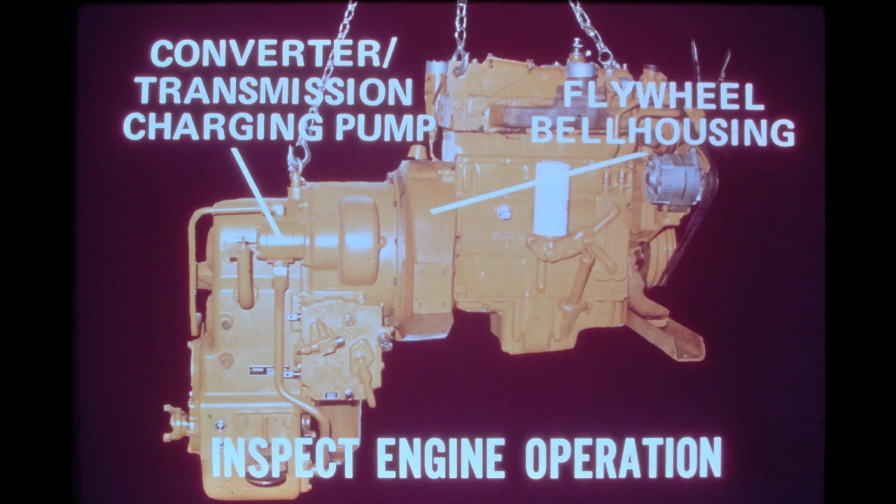After performing preliminary inspections and observing the machine in operation, the serviceman should know if the problem affects one circuit or if the total system is affected. He should also know what individual components are included in the affected circuit and what is the proper functioning of each component. A sluggish response of the torque converter transmission system could be caused by an engine problem rather than by the malfunction of a component in the system.